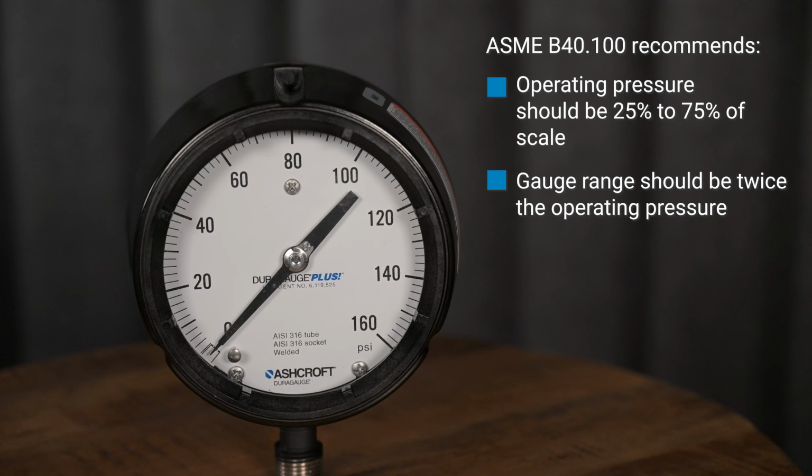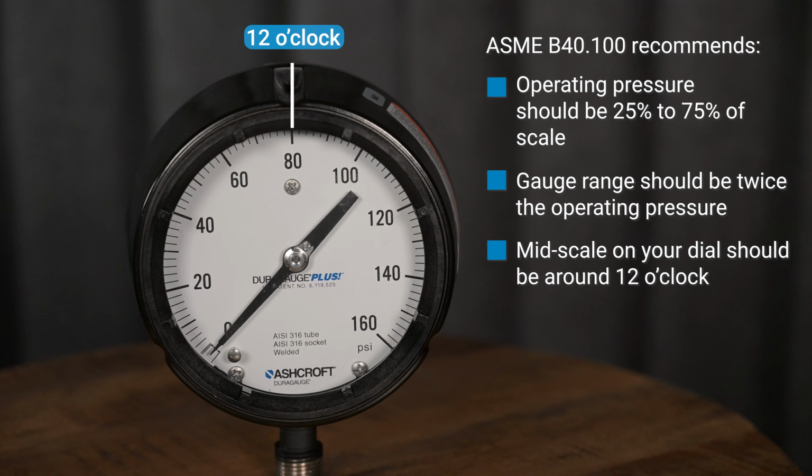The first step in selecting a pressure gauge range is to understand the operating pressures of your process. Ashcroft follows ASME B40.100 standard, which recommends the following. Operating pressure should be 25 to 75% of scale, and the gauge range should be twice the operating pressure. Ideally, the mid-scale on your dial should be around 12 o'clock, or the mid-scale of the full-scale gauge span. If pulsation is present, the maximum operating gauge pressure should not exceed 50% of the full-scale range.